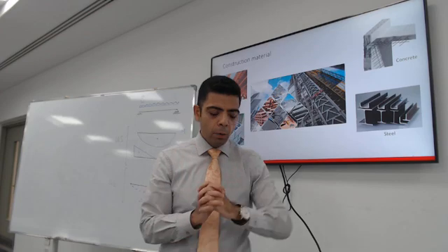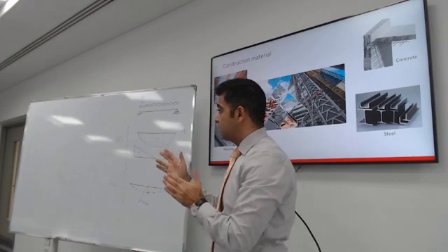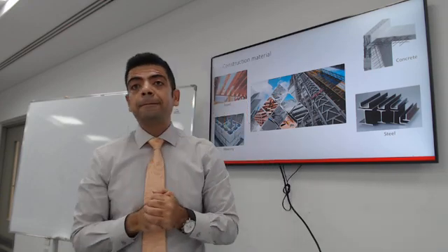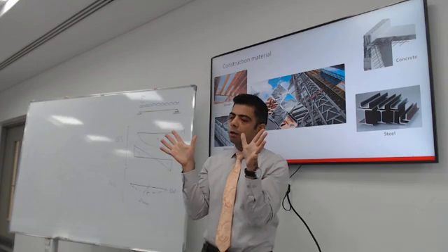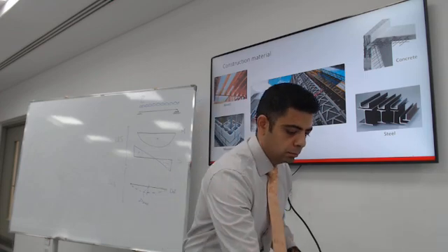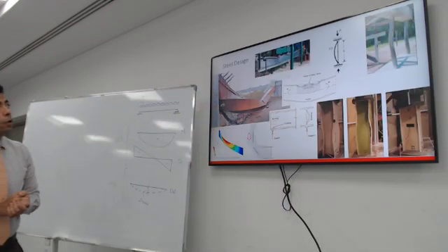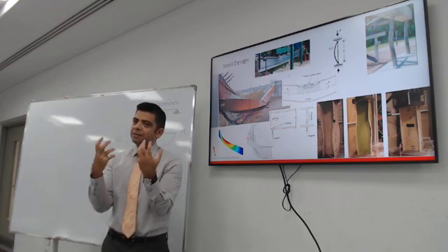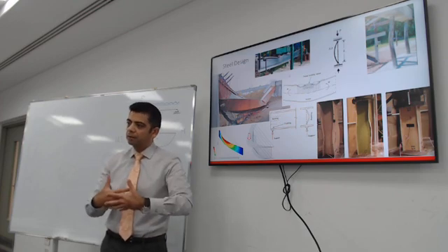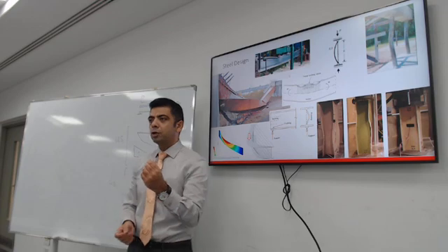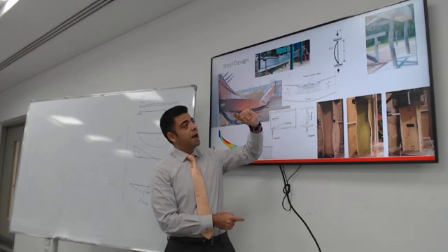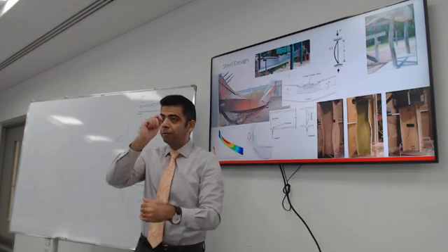All right, before we switch gears and we get some examples of the specific design I want you to do, I want to have a general idea about how you design a section of steel. Well, we might as well understand how a steel section might fail. There are different ways that a steel section could fail. So when you're designing it, you're making sure that it's not going to fail like this. It's not going to fail in compression like this. And it's not going to buckle like this. And then you fulfill the checklist.